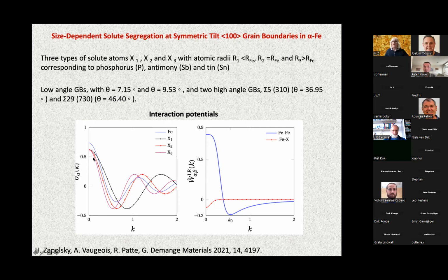So we fitted our short-range interaction, as you can see here, which is different. It's normal because we have different sizes of the atoms, and the short-range interaction fits this difference in size. And for the long-range interaction, for the iron-iron, of course, it's the BCC crystal, so it's one minimum potential, which is fitted, as I said, on the molecular dynamics simulation. And for the AB, we choose a complete separation. It means that it's an immiscible system because its minimum is situated at k equals 0.